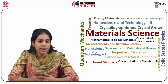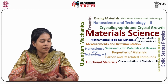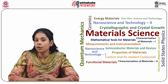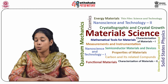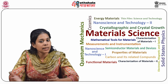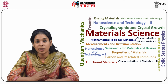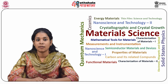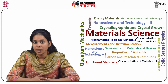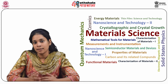During solid state sintering, no significant amount of any liquid phase is present. However, in many cases, a liquid phase is present during sintering. So the presence of liquid phase in these cases gives a high sintered density at very low temperatures. In this module, pressure assisted sintering and liquid phase sintering will be focused on and discussed.